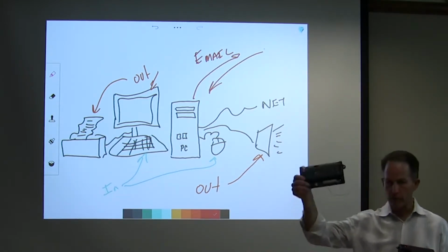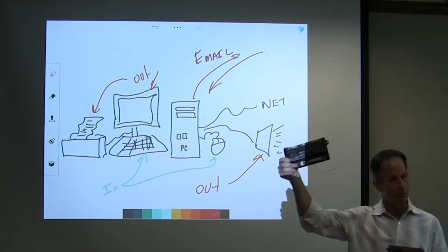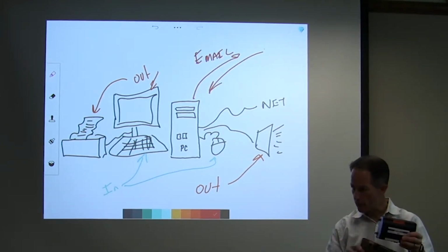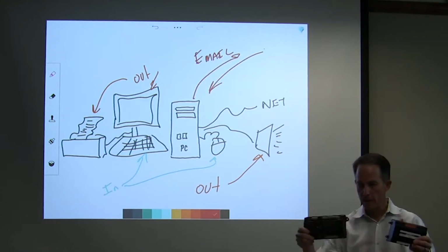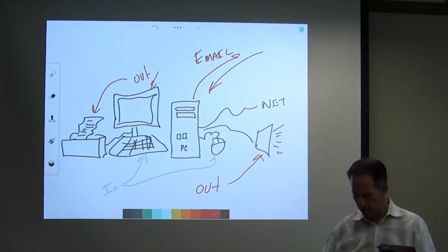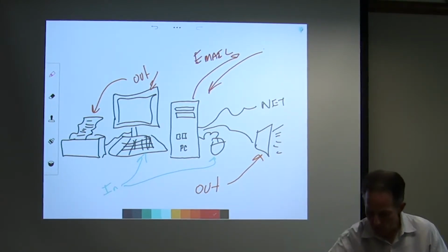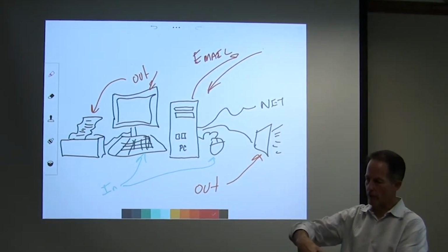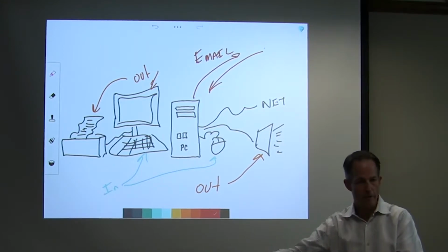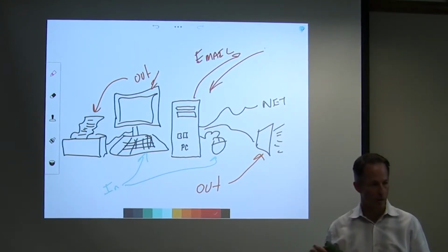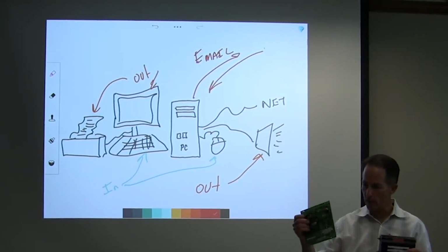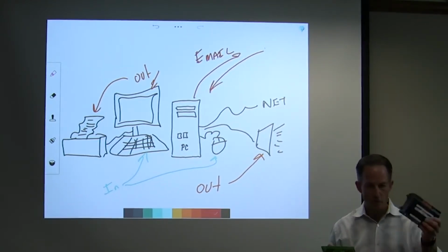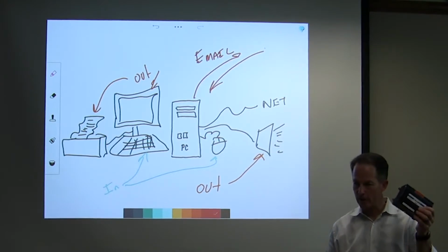So the Delta controllers are BACnet based. That's the communication protocol. They can be tied in through a communication trunk or a comm line, and information is brought in. Those can talk to Smart 2 on the very same Jace, or like this has got the little orange connector, that'll talk to the Distech, which is LonWorks. You can have all three off of the same Jace, and they can share information and data between them. So that's kind of what our Jace is key for.